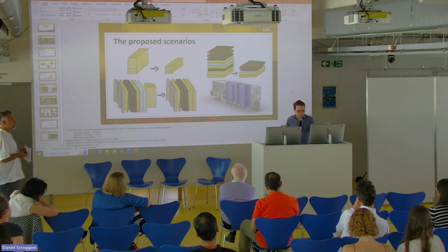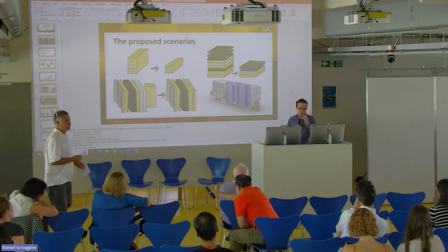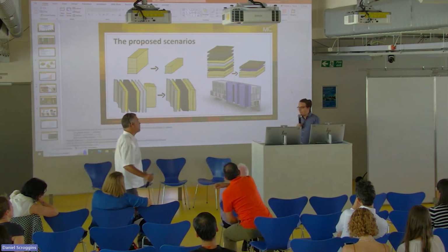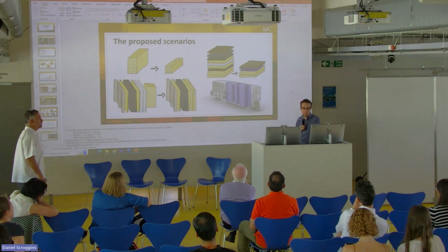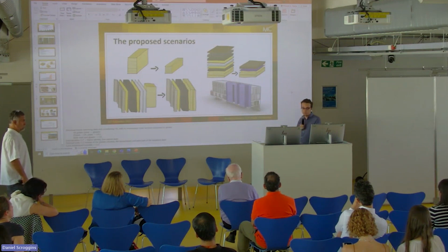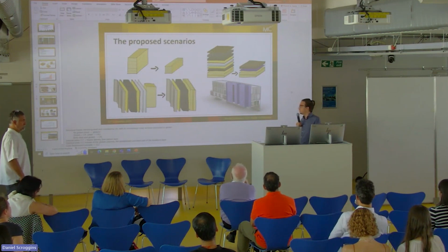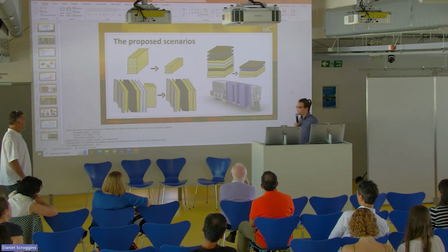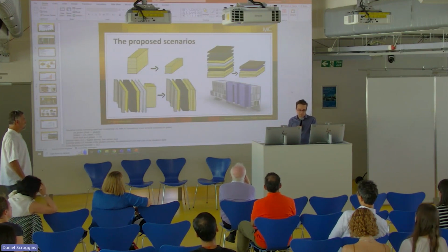It's something that I was interested in because the main issue of timber construction is indeed the lack of thermal mass, which is a big issue for operational energy and therefore operational carbon. In this case, I dimensioned the new CLT wall to get the same U value as the wall before. And to do this, I reduced the amount of the mineral wool insulation that is the purple layer there. But in my simulations, I didn't really find any difference in this case.